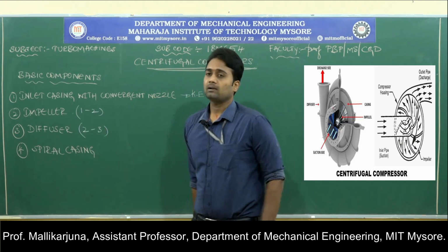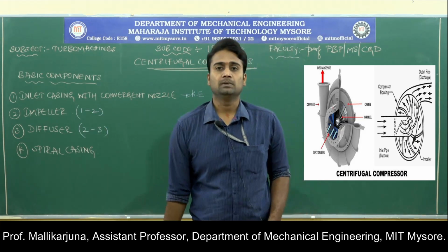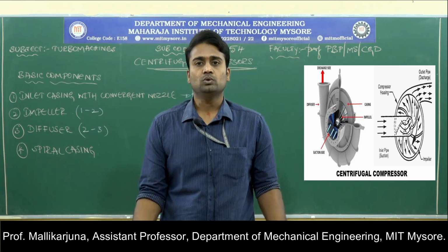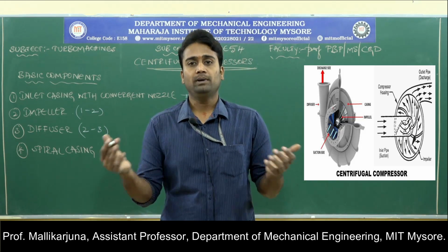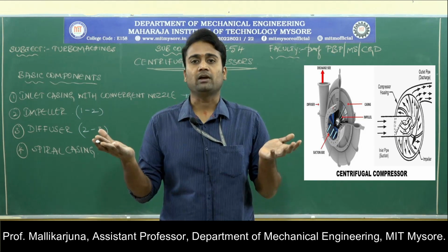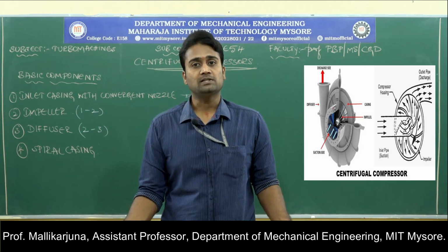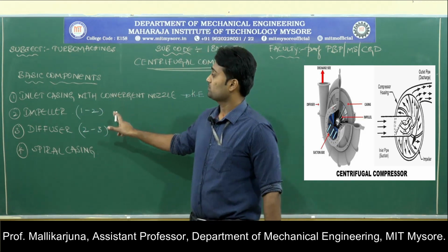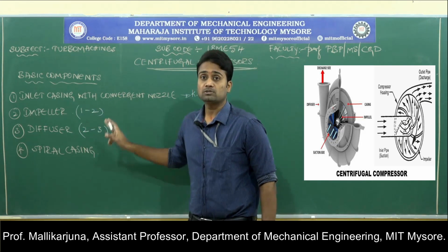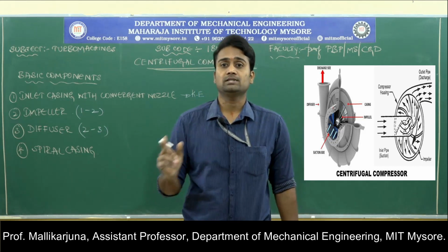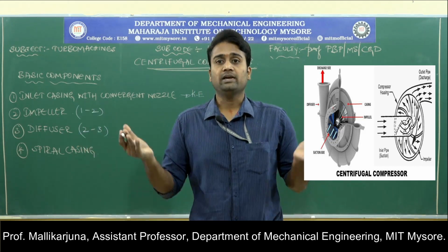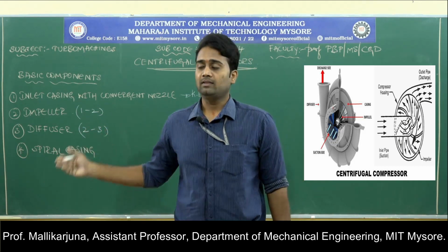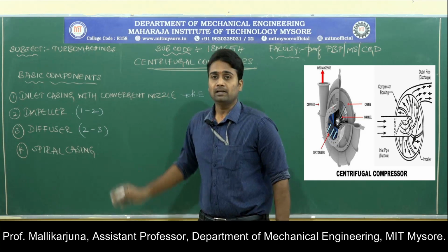Next, impeller. Here we need to understand the term impeller. An impeller is a device which is used to impel the fluid. Impel means lifting, or we can say raising the pressure. So the device which is solely responsible for raising the pressure of the fluid is called the impeller. Lifting action or raising the pressure is what impelling action is, and the name of that device is impeller.